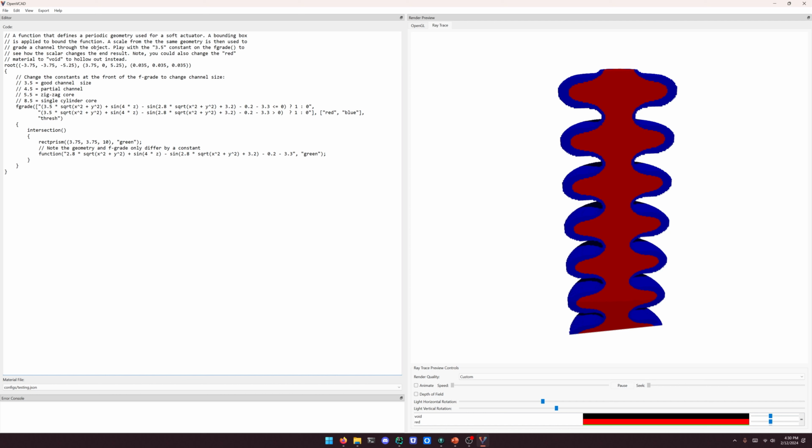And notice how I'm using the threshold mode here. So threshold is going to say whatever material is dominant in that region is whatever material it should be. If I change this to probability and we re-render, you're going to see,